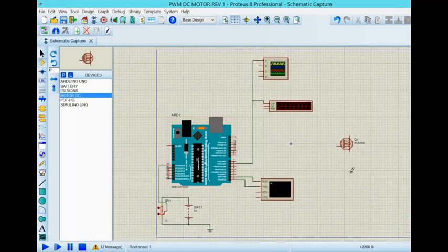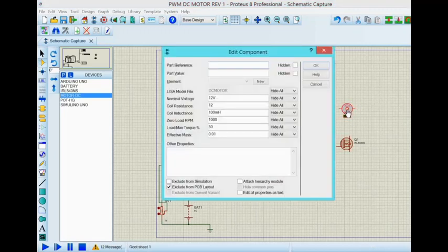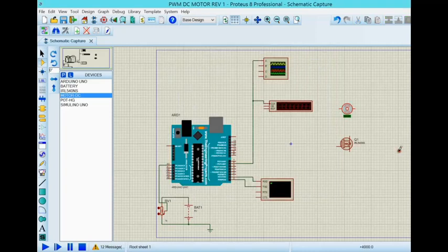And a motor. So let's see. Let's add that here somewhere. Okay, that will do. Let me double check on this one. So it's a 12-volt motor. Good. Coil resistance 12 ohms. Load max torque, let's move it to 80. Kind of higher. Let's see if it's okay.